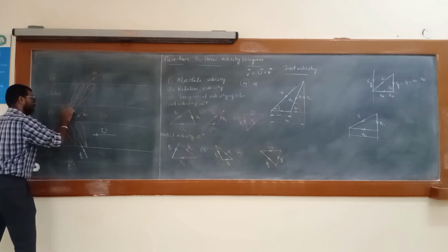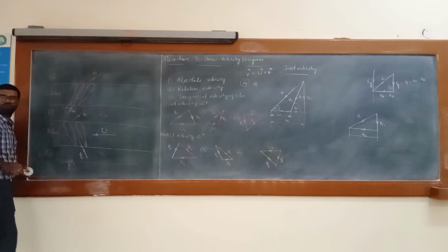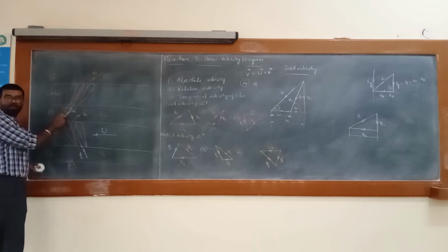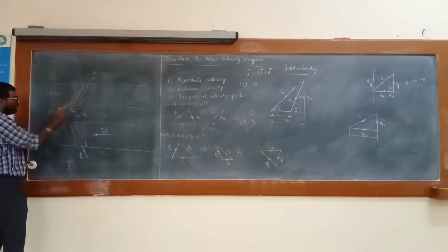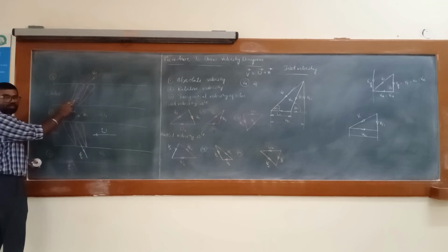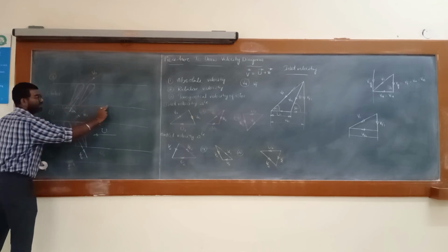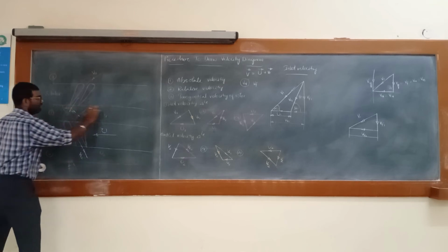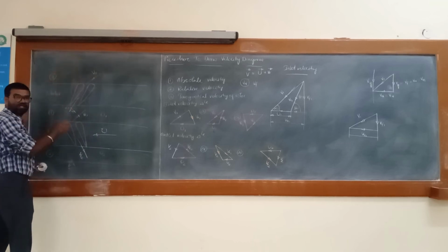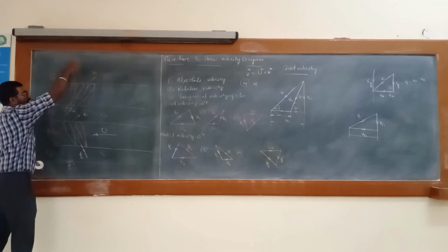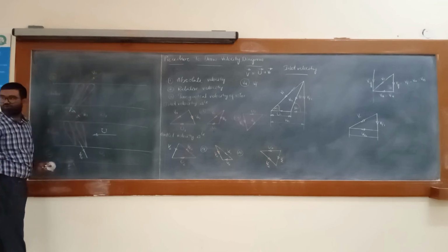This is also known as nozzle angle at the inlet of the rotor. That is, the angle made by the tip of the nozzle with respect to the tangential direction. Okay, these are the tangential directions. The vertical will be the axial direction for axial flow machines, radial direction for radial flow machines.